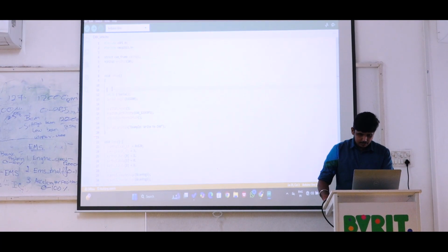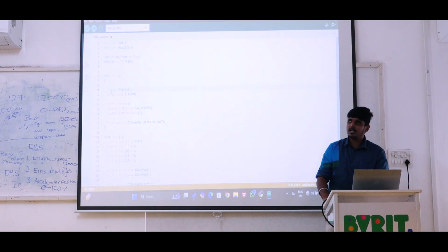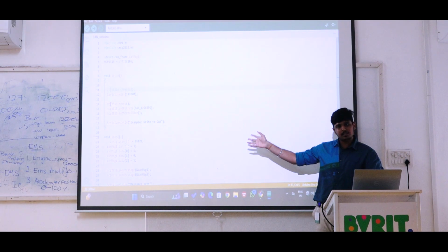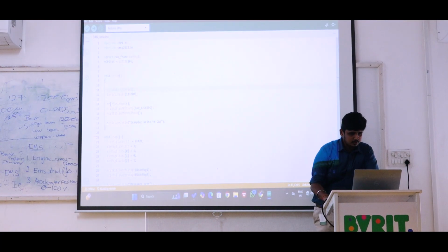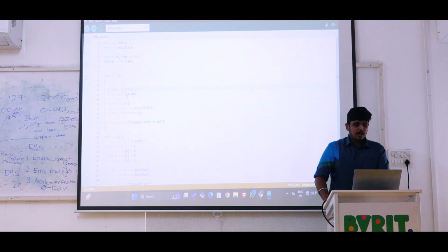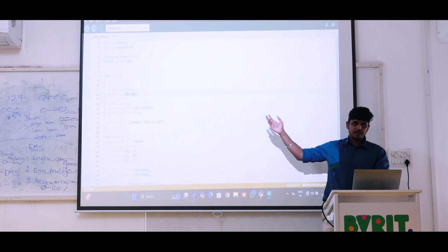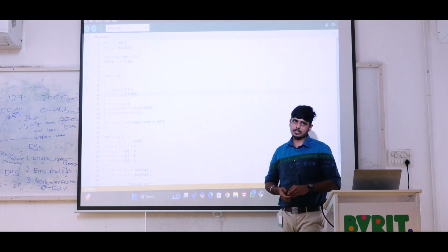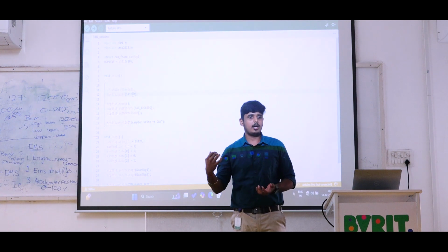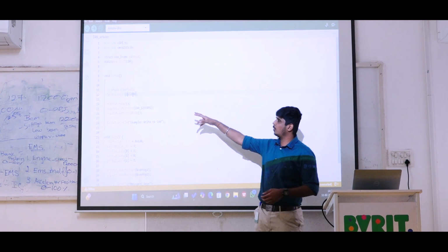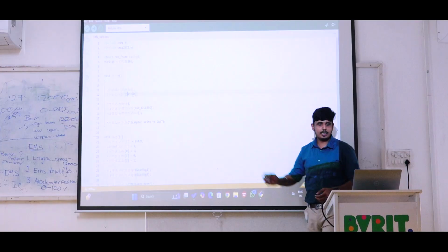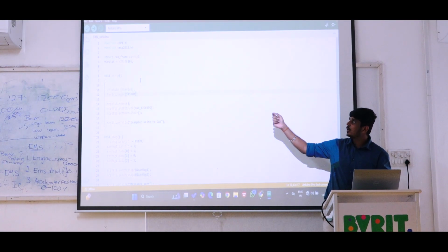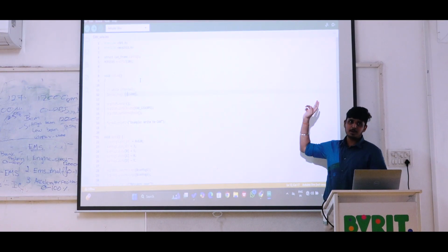This while serial is nothing but just running the loop again. If it is not here, it is also running the loop. I am just commenting that. We are using baud rate as 115200. In UNO we will use 9600 also. We are using CAN now, so that's why we are using 115200. Whatever baud rate we use, that baud rate also you need to set in the serial monitor.